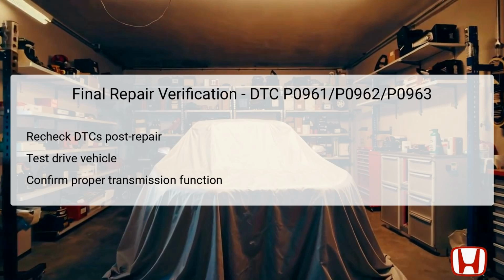After completing necessary repairs related to DTCs P0961, P0962, and P0963, it's crucial to validate the repair effectiveness thoroughly. Start by rechecking the DTCs using the HDS to confirm that no trouble codes have returned. Once confirmed, conduct a test drive under varied driving conditions to observe the vehicle's performance. Pay close attention to how the transmission shifts. Ensure it engages and disengages smoothly without any roughness or delays.